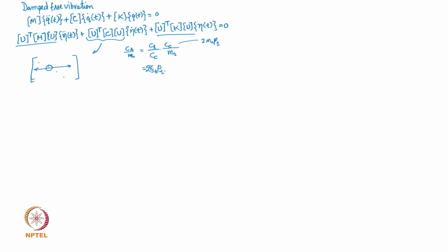Okay. So, then we say that this damping matrix can be replaced by modal damping ratios, and each of these modal damping ratios will have to be identified. So, each of these diagonal terms will now be quantified through modal damping ratios, and these should be called the equivalent viscous damping factors.